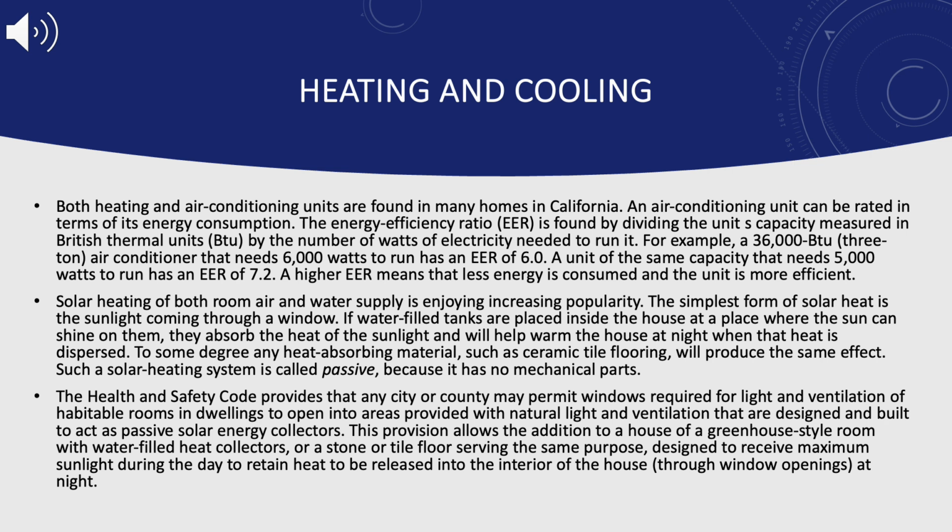The Health and Safety Code provides that any city or county may permit windows required for light and ventilation of habitable rooms in dwellings to open into areas provided with natural light and ventilation that are designed and built to act as passive solar energy collectors. This provision allows the addition to a house of a greenhouse-style room with water-filled heat collectors, or a stone or tile floor serving the same purpose, designed to receive maximum sunlight during the day to retain heat to be released into the interior of the house through window openings at night.